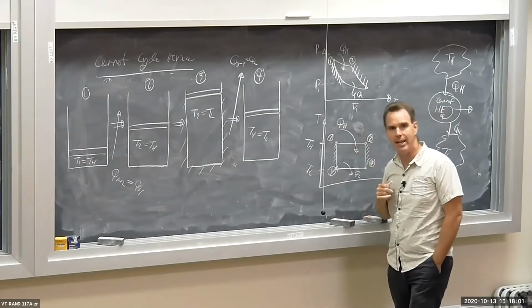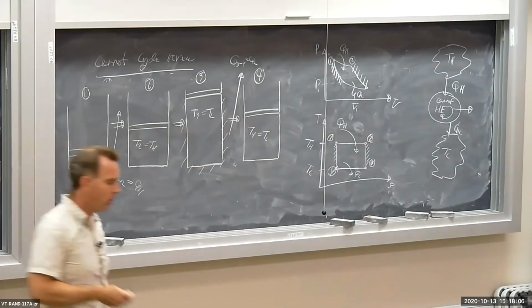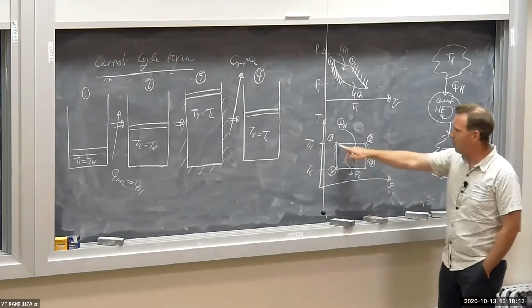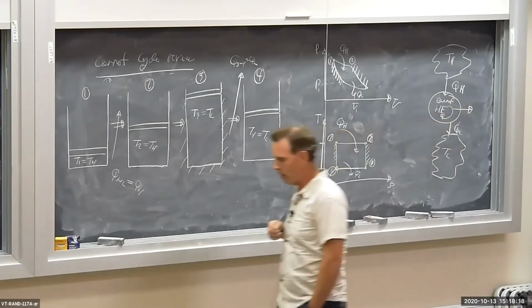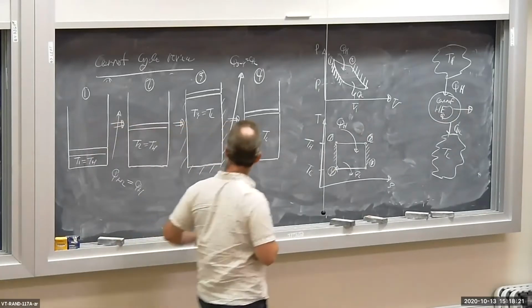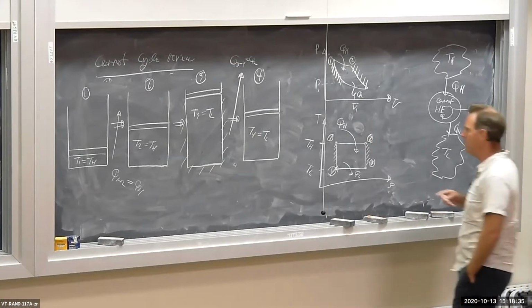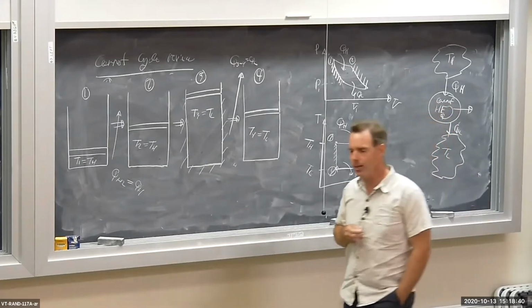Entropy is being brought into the system, the air, the gas, or whatever the working fluid is. So if entropy is being brought into the system, that means entropy goes up. As we go from state 1 to state 2, entropy goes up, temperature remains constant. That's indicated on the TS diagram. Then from process 2 to 3, we wrap the piston cylinder device in some kind of insulation. No heat transfer, and then we expand the gas down to the low temperature reservoir temperature TL. So 2 to 3 is adiabatic.